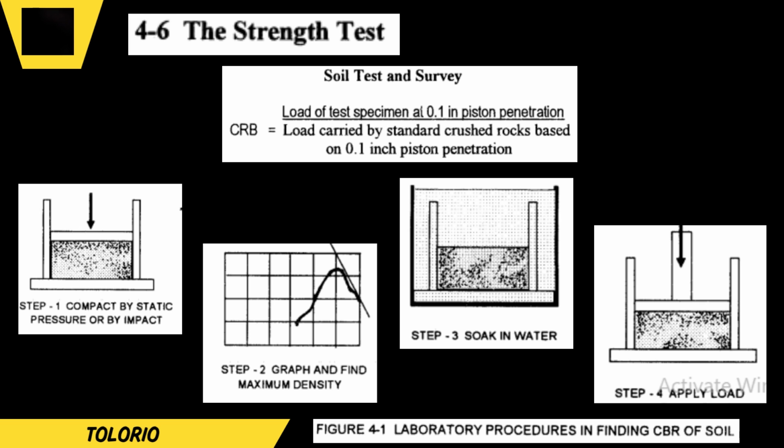Procedure in finding CBR of soil. Step 1. Compact by static pressure or by impact. Step 2. Graph and find maximum density. Step 3. Soak in water. Step 4. Apply load.